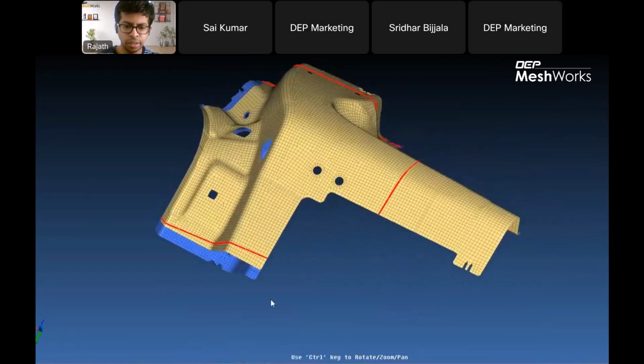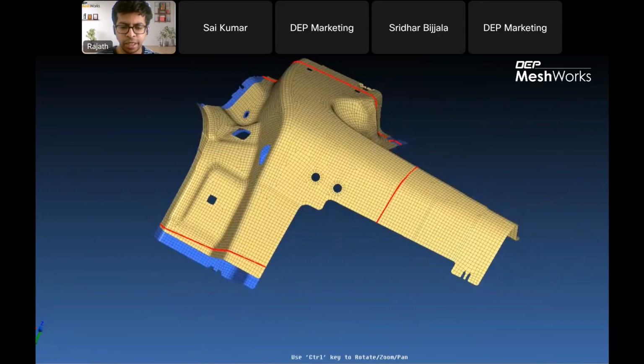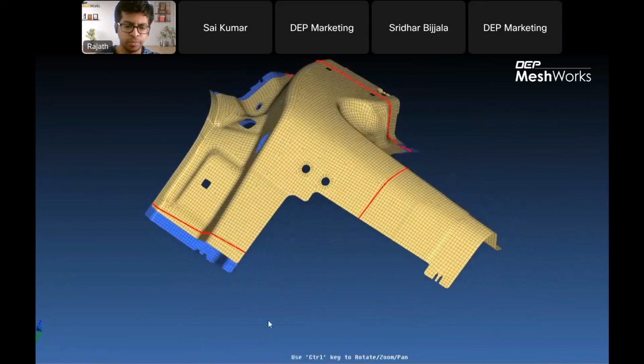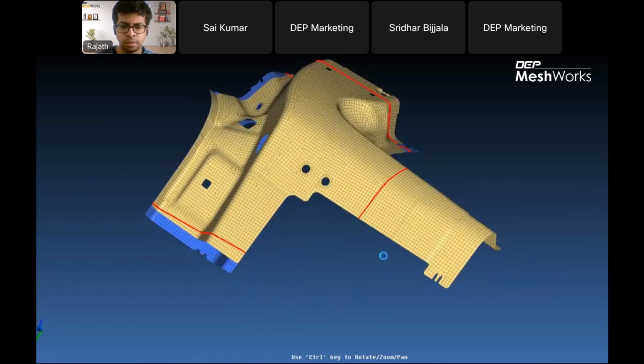around the component, and the tria mesh will be created by doing an offset. Meanwhile, in the next step, what we would be doing is creating sidewalls around these 1D edges. The final intention is to create a closed structure so that we can create a design space with tetra mesh. So that's the process we'll be using.